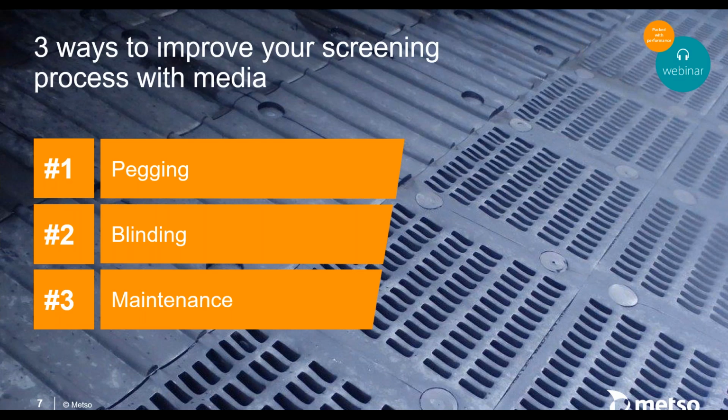Basically, the 3 challenges that we are going to look at today are these 3 that you see on the screen. The first one is pegging. For those of you who are not familiar with it, that is when rocks get stuck in the apertures, in the openings, and they are then unable to leave, and they will sit there in the screen cloth, and eventually, if it's really bad, this can lead to, let's say, total non-performance.